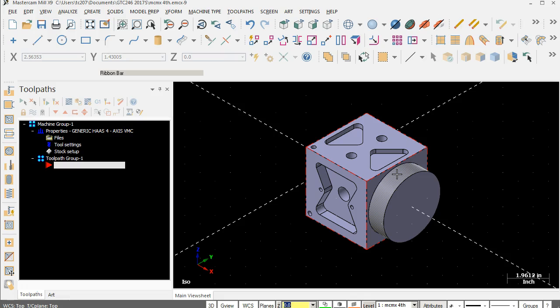Not always apparent. It depends on how much geometry you have and cycle times. Typically, I don't want to do very many tool changes. I would rather index this around with the tool change, get it all in one shot, go to the tool change, index to the next operation. I think as a general strategy, most machinists and programmers are going to go that route. There may be times where you would want to do everything on this face, but you're going to have a specific reason for it. Okay.